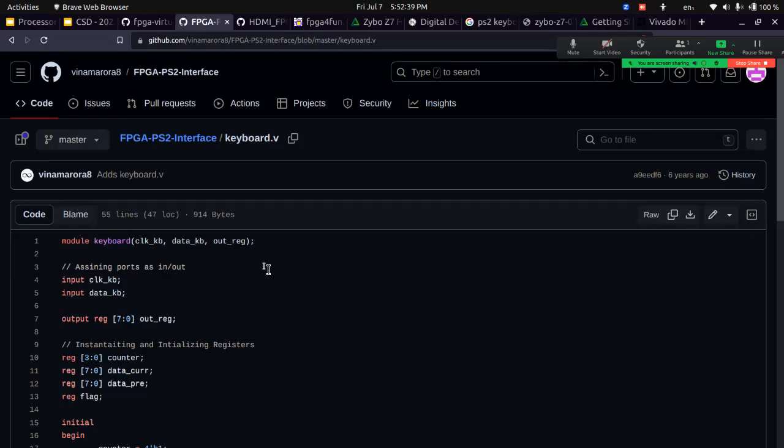If there is any of these kinds of interrupts, then it will not execute the instruction. Instead, it will directly jump to the interrupt handler. So in every fetch stage of every instruction, it will check whether there is any interrupt. Only if there is no interrupt will it go to execution.